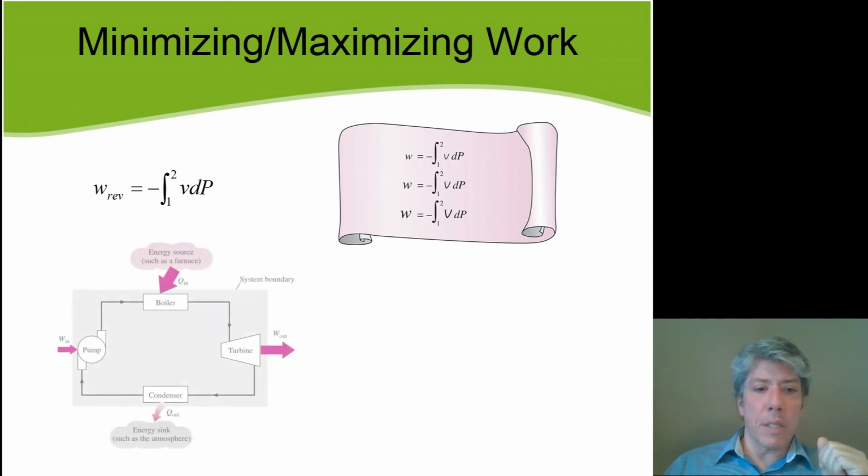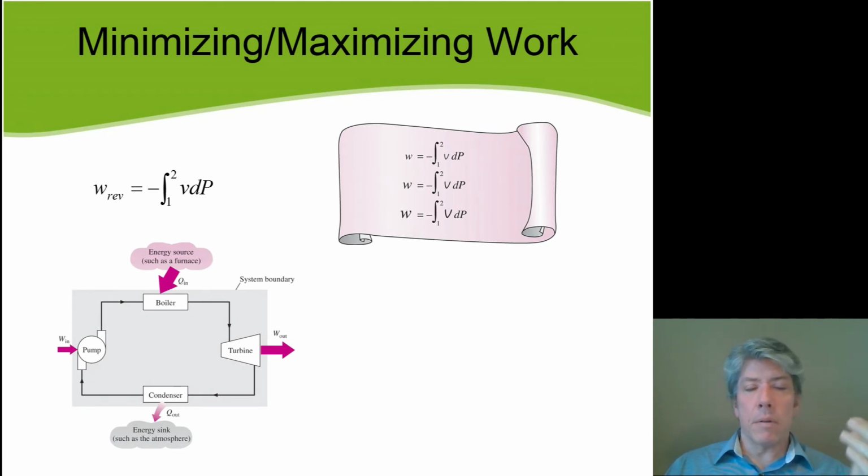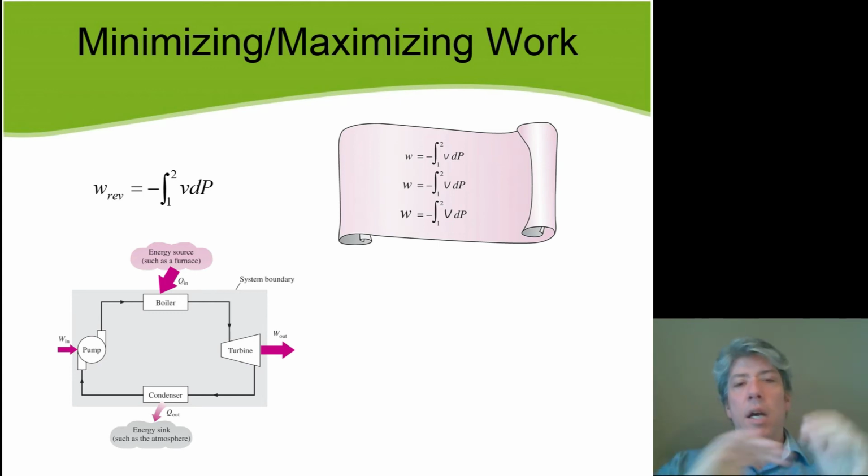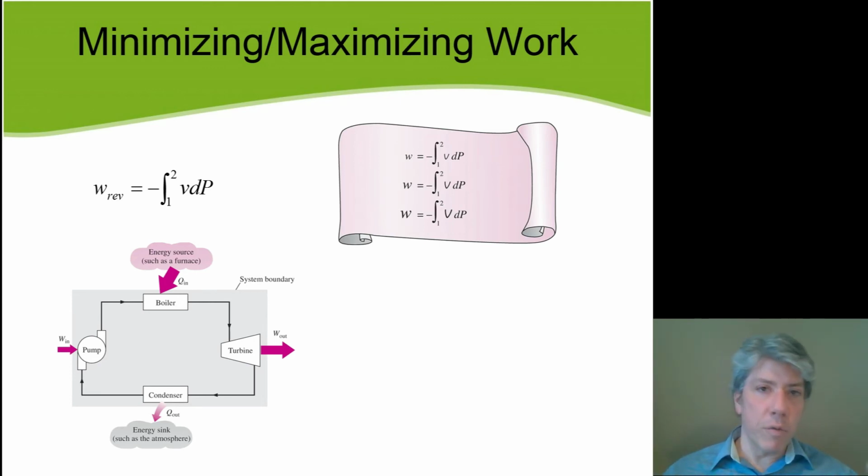And this should help explain why, when we considered a steam cycle before, where we've got a turbine and a pump and all these things, remember, we considered this and we said, well, this seems crazy. Why do you boil off the water, right? It's in liquid form. You boil it off, so there's all this energy you dump into it to change the phase, let it go through a turbine at high pressure, and then run it through a condenser, where the condenser does nothing more than condense it back and change it from vapor into liquid and throw away all that energy.